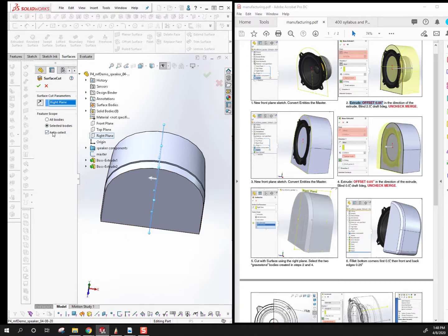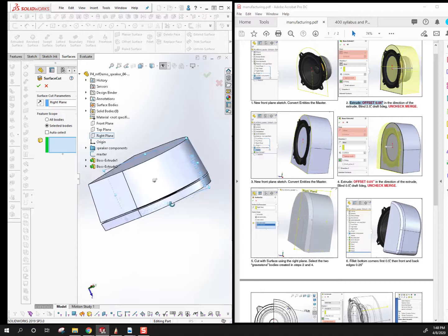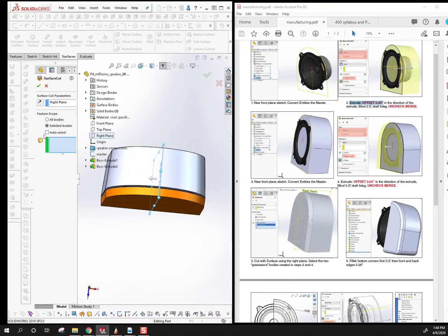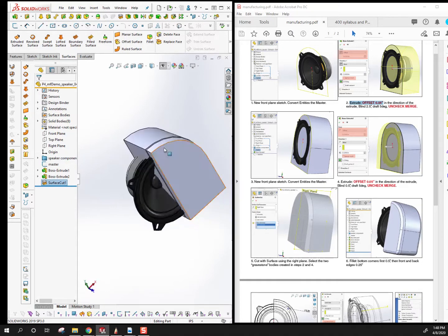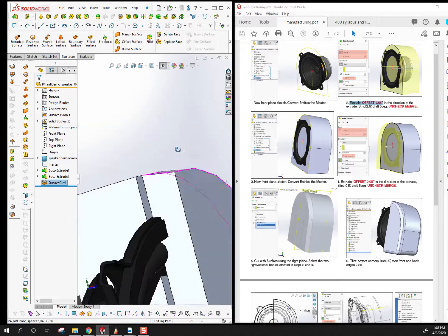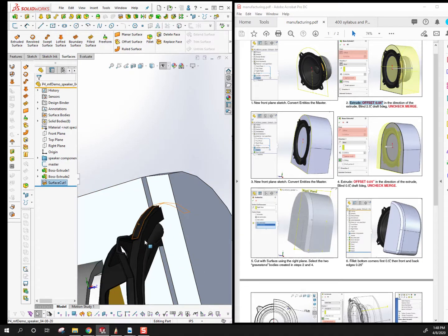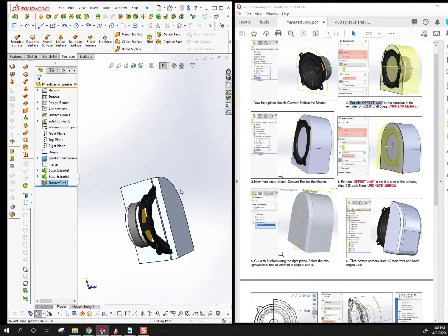And here, once again, in the feature scope, you want to manage what's cut. And this is what's kind of new and different for Project 4, managing what is cut. You don't want to cut the components by accident. So instead of auto-selecting this, I'm going to click in this box, and I'm just going to select both of these bodies here, both the back body and this front plate, and I'm going to click this checkbox. And now you can see we cut half the bodies. So now as we work on this detailed part line, we only have to do half of it. We don't have to do all of it. And we will end by mirroring the object.